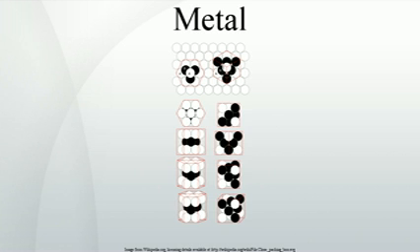Examples: the transition metals, such as iron, copper, zinc, and nickel, are slower to oxidize because they form a passivating layer of oxide that protects the interior. Others, like palladium, platinum and gold, do not react with the atmosphere at all. Some metals form a barrier layer of oxide on their surface which cannot be penetrated by further oxygen molecules and thus retain their shiny appearance and good conductivity for many decades, like aluminium, magnesium, some steels, and titanium.